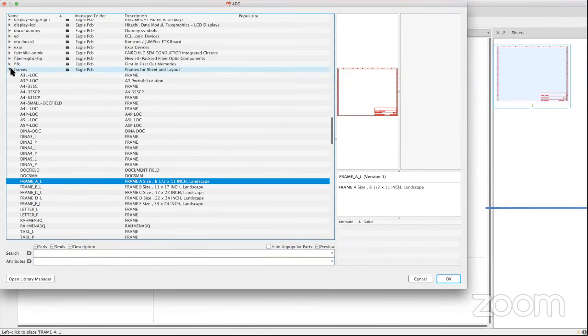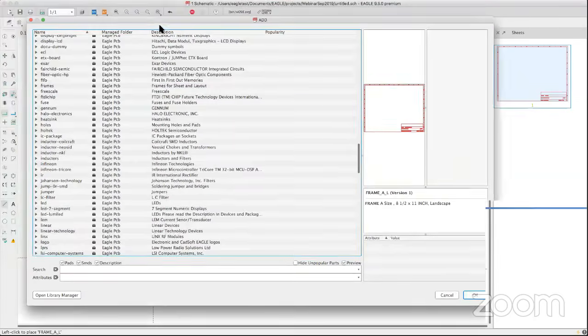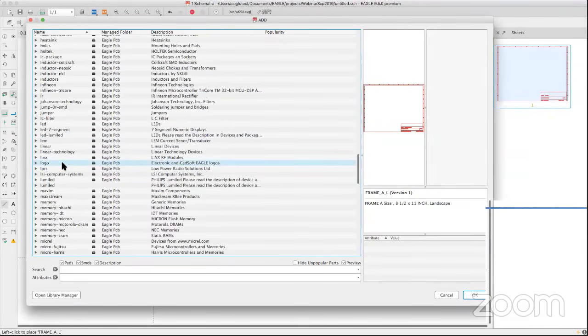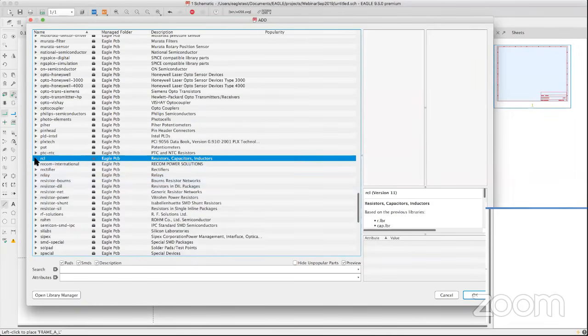So in my design, it's just using a 555 timer to enable some LEDs depending on the value of the resistors. It's the flashing that's going to be happening on the LEDs. So let me just go ahead and select another component. And in this instance, I'm just going to use the RCL library. So let me go down to the R's. This is the RCL library.